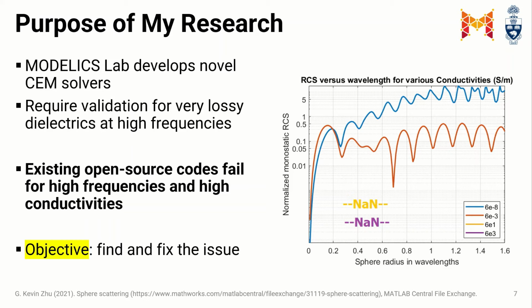One project in collaboration with Advanced Micro Devices is involved with modeling the crosstalk and electromagnetic noise inside central processing units. This is a very challenging problem because semiconductors behave as lossy dielectrics at gigahertz frequencies, and even partially conducting elements begin to radiate electromagnetic noise.